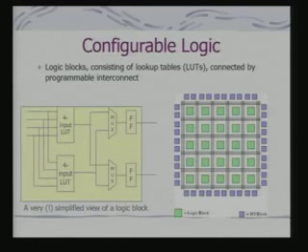So, what are really FPGAs? FPGAs, we said, are configurable logic, and here we are showing a very simple example. Okay? In fact, this is a basic logic block. You have got a 4 input LUT, so it is a kind of combinational circuit. Okay? This is another 4 input LUT. So, depending on the 4 inputs, you can synthesize any 4 input function. The basic idea is that. And this is a multiplexer. Depending on control inputs, you can choose the functions from these 2 blocks, and these are the flip flops.